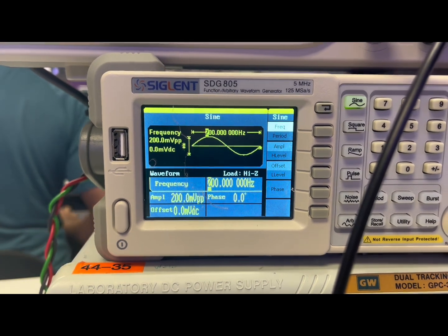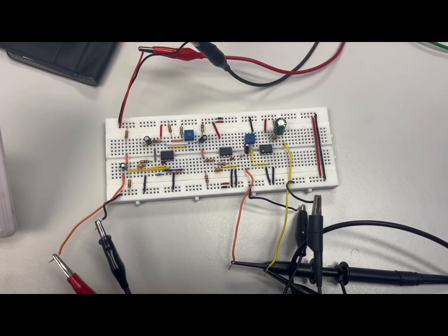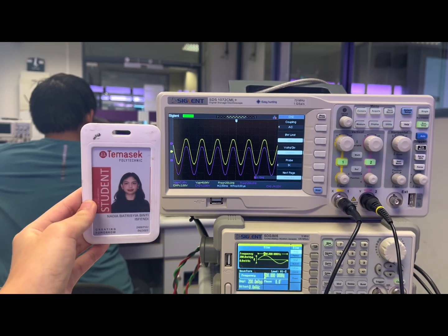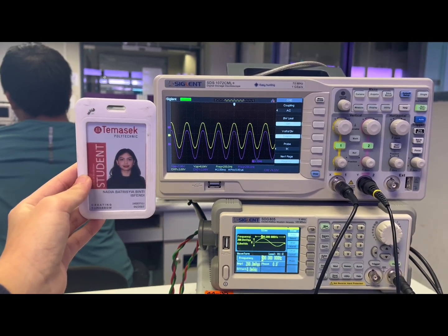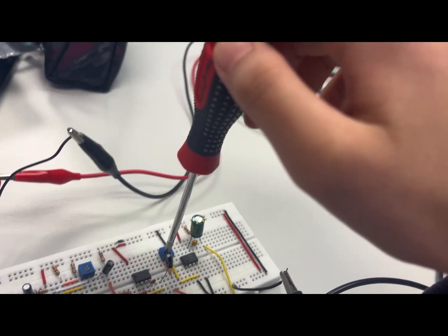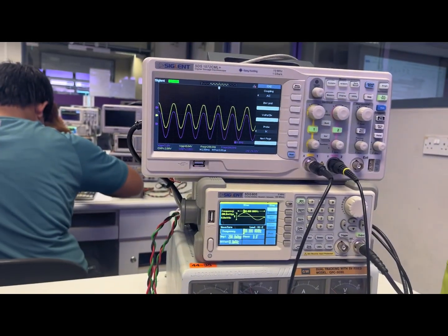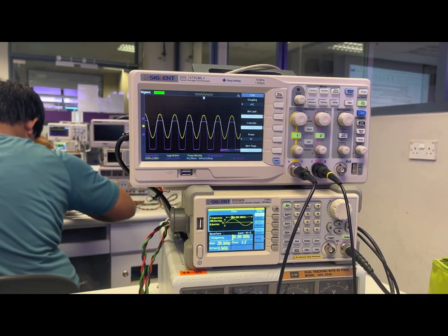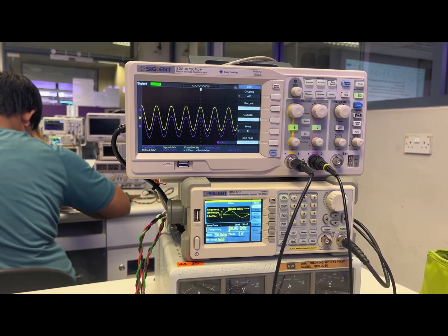Set the frequency to 200 Hz without altering anything else. The output voltage is around 7.36 volts. By adjusting the trimmer at P2, we can also control the output at TP5. The final output will then be the maximum sine wave attained without being saturated.